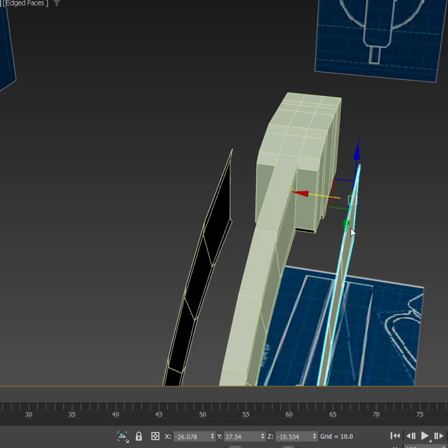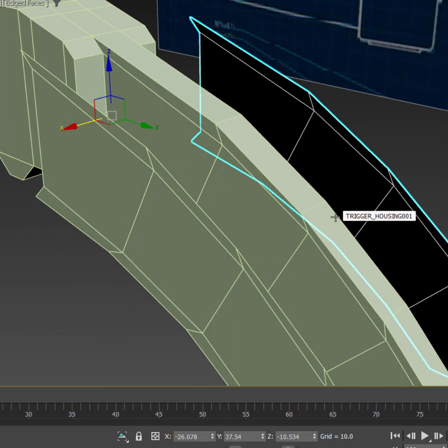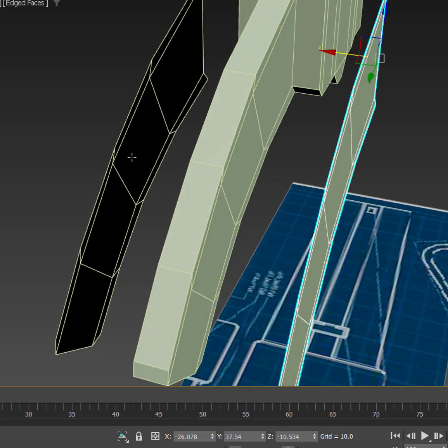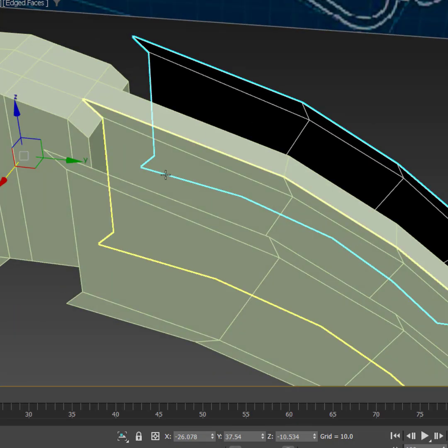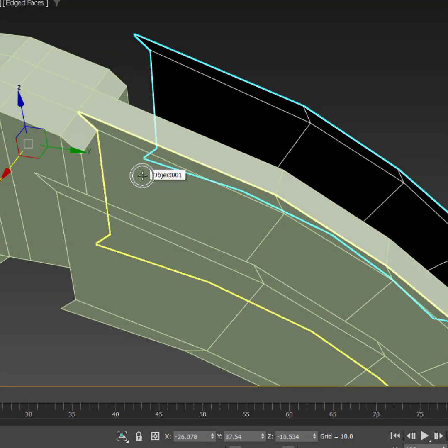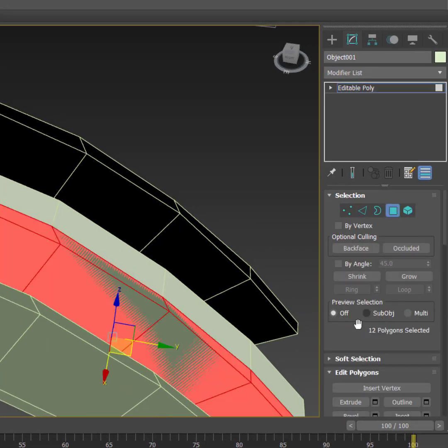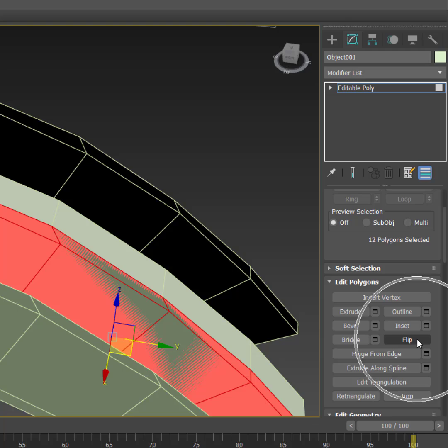Okay, so the next thing to do is let's combine these two. So remember, you cannot bridge this to solidify this part, no? If they are not like faces. So that means if this is black or negative, they should also be black and negative. So I'll select this. I'll go to polygon selection, Control E, polygon selection, and then you have your flip here. So now it just flips.